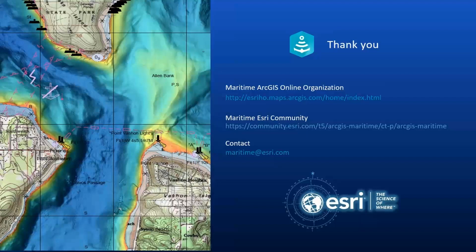Looks like I see a question about, are the contours smooth on the safe side? Yes. So if you use the smooth bathymetric tool, that smooths the surface in a shallow biased way, and then the contours are generated from that smooth surface. So the surface itself is what's being smoothed in the safe fashion.